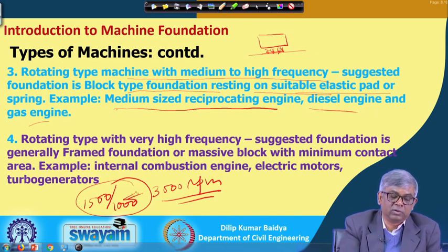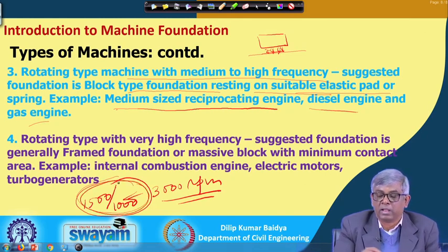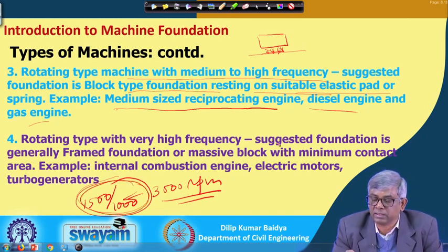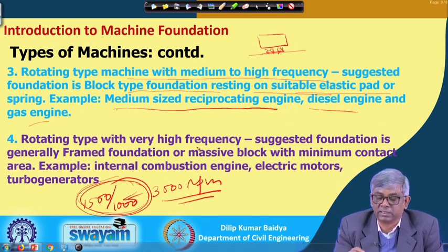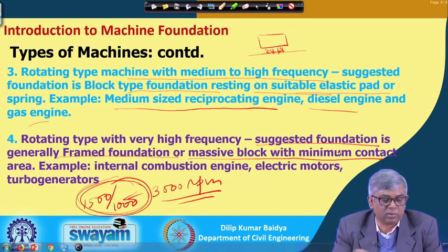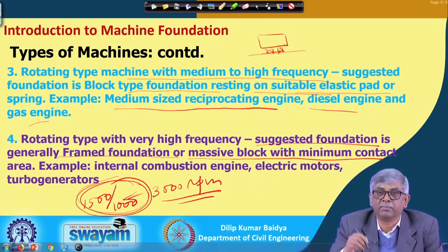That means it will be half or even lesser than that. So, this is under tune design, and if you do that, because of that you can see for high frequency machine, the suggested foundation is generally frame foundation or massive block with minimum contact area. So, generally frame foundation will be there.